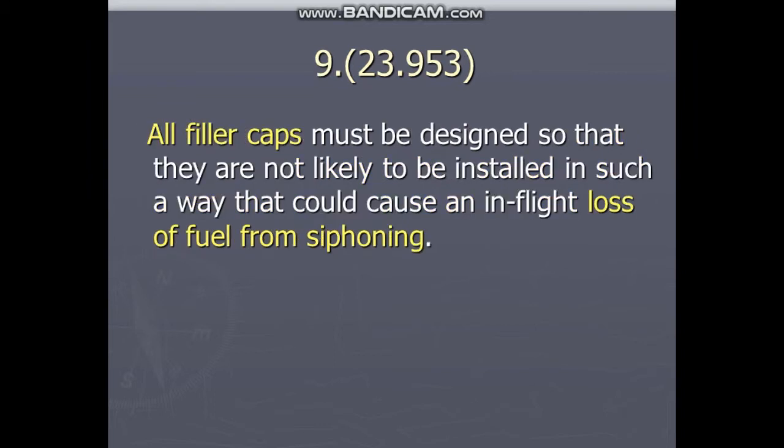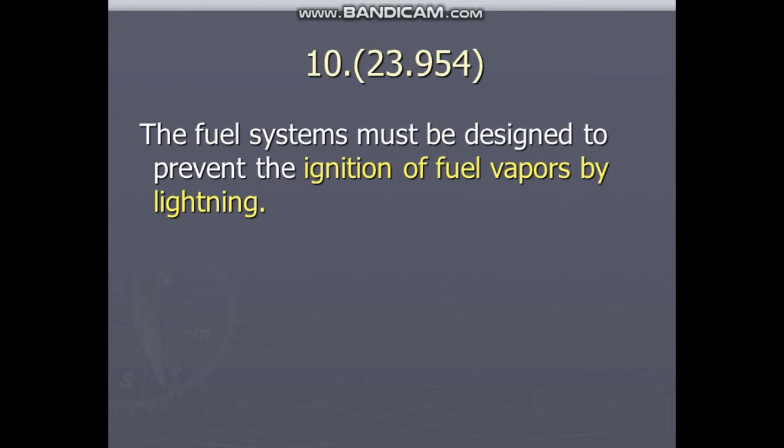Number 8. All filler caps must be designed so that they are not likely to be installed in such a way that could cause an in-flight loss of fuel from siphoning. Number 10. The fuel systems must be designed to prevent the ignition of fuel vaporized by lightning.